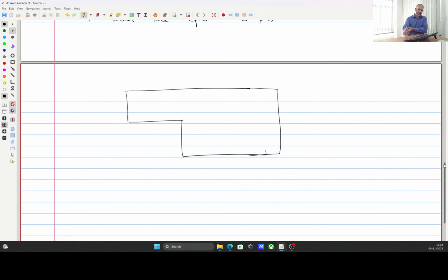So actually, what is known? We know that on the walls we have a no slip condition, and it's not a permeable wall, so that means that no flow can pass through the wall. So if it's a non-permeable wall, then V is equal to 0, and if it's a no slip condition, then U is also equal to 0. So we get this same no slip on all the walls.